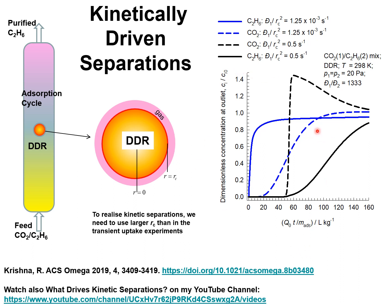If, on the other hand, the diffusional time constant is significantly larger, say 0.5 per second, the breakthroughs are shown by the black lines. The continuous black line is for C2H6, and the dashed black line is for CO2. In this case, CO2 is the component that breaks through earlier. This is not a scenario that is desirable because we would like to have purified C2H6 leaving the adsorption cycle.